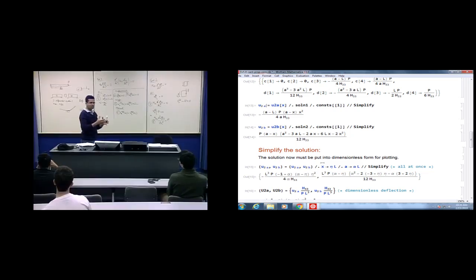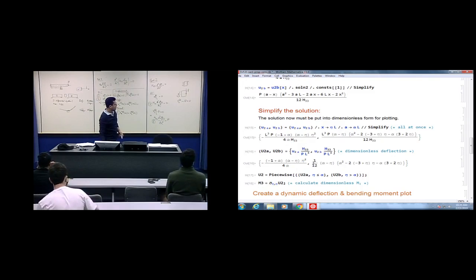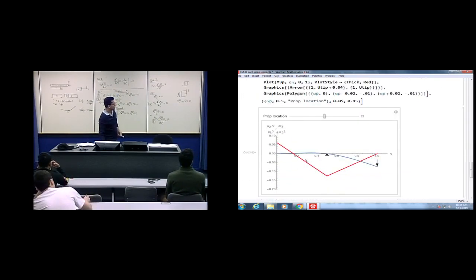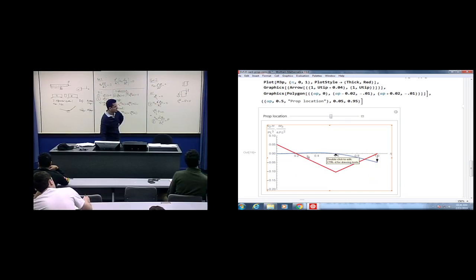Okay, that function for a particular displacement is valid on the domain of those displacements. And then I'm just plotting the displacement here. So if you move the support, let's say the support is in the range of 0 to 0.5, there is hardly any effect. For example, if you have support at 0.5, the P causes some effect, but essentially your cantilever beam is being helped by putting that support.